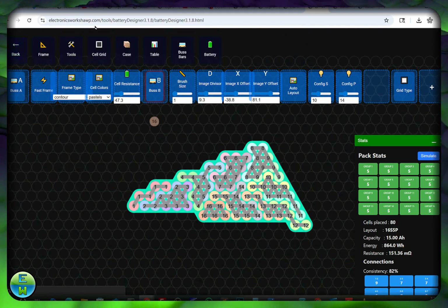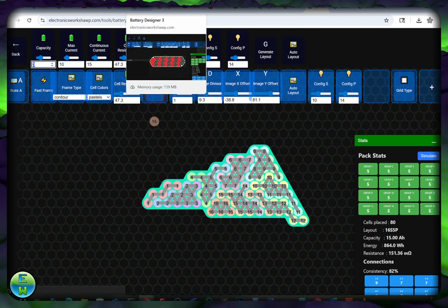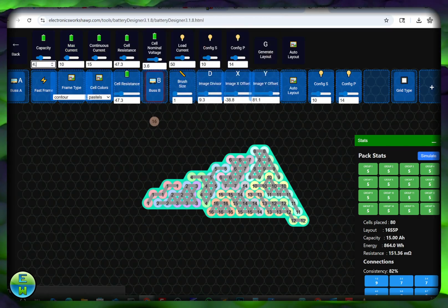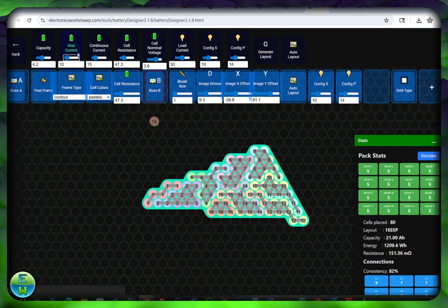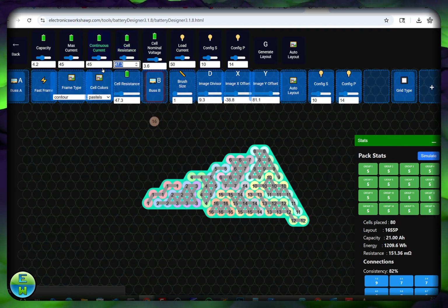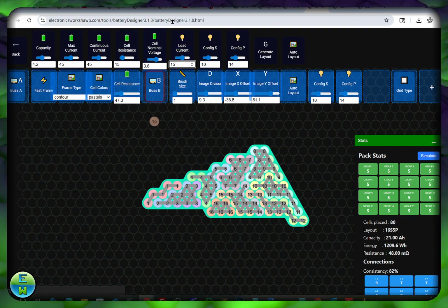If you go to parameters and battery, you can put your actual cell in. So let's say it's a Molicel P42A. So you can say it is 4.2 amp hours. You can do 45 max, and I think they just rate it the same, right? 45 continuous on those cells. At least most places I've seen it. And the resistance, those are like 15 or something like that, milliohms. That's already correct. And we can do the simulation for 150 amp load.